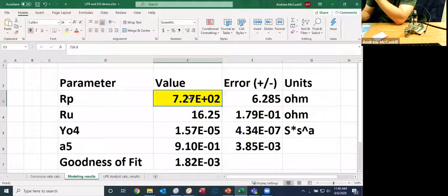So would you say there's a discrepancy there, because one value seems to be almost twice as much as the other? Depends on what you define as really good data or not. I expected the values, based on what I ran yesterday, to be closer to about 3 to 5 kilo-ohms. So seeing this value right here tells me that the surface that I isolated, compared to the surface that I ran yesterday, there's something different. I'm using the same solution, the same setup, same cell. So I'd point to something being different on the surface of the electrode itself.